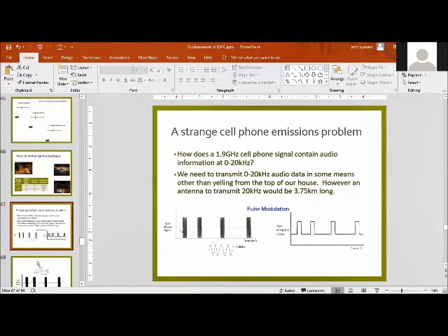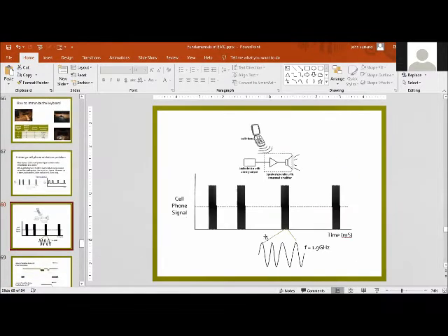So it has a very high frequency signal, but it repeats at a very low frequency. And what that does is induce some sort of waveform, like I show on the right at the bottom, into the speaker somehow, and that's what you're hearing: that low frequency repetition. All the high frequency stuff disappears in the process of putting the noise into the speaker, so it's rectified and you get this low frequency.